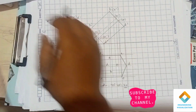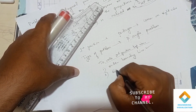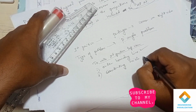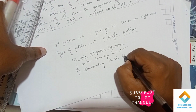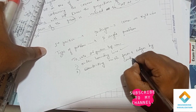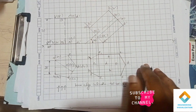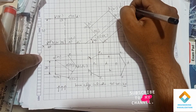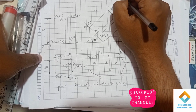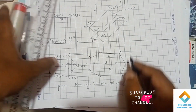Okay, now the second step is writing the visible faces and the edges. So we have to write or construct the visible faces or the edges. Okay, that is our second step. So visible faces and edges we will be constructing using continuous line. You can see as we are looking at this diagram from the top view, this position. So as we look from the top view, this face is visible, right? From the top view, this top face is visible.